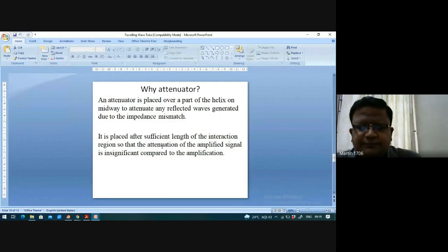The echo will come. Similarly, in the middle of this helical structure, some signals may bombard each other and get reflected back due to impedance mismatch. So this will happen. We have to avoid this type of reflection effect in your transmission line.